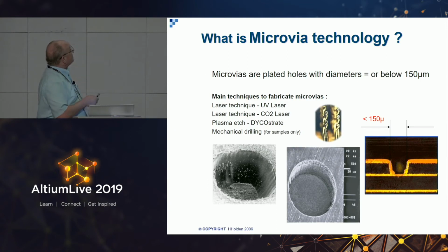Today is mostly about microvia technology, or these little tiny guys right here. Believe it or not, in North America, we have people that mechanically drill these. Do you have any of that in Europe, where companies actually mechanically drill the blind via? We actually have a couple of companies that have no lasers. They mechanically drill these things, which is not easy, but does work.